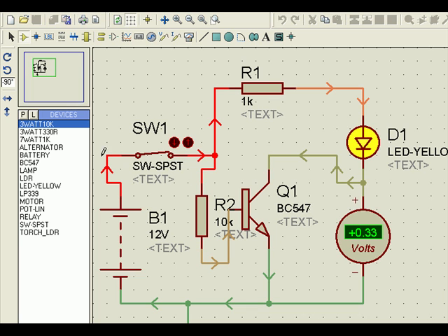So when the current flows this way, then only this current starts flowing this way. And once the current starts flowing, these 2 points are just like a switch. Just like a switch means once the switch closes, the voltage drop across this is nearing 0.